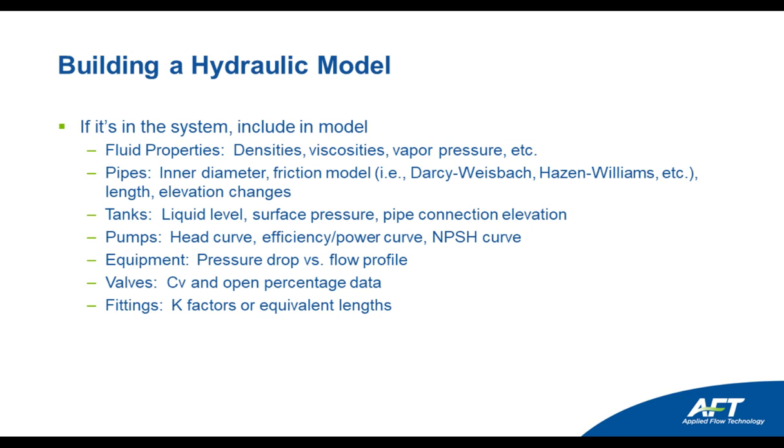Now, let's say that you have included all of this information in your hydraulic model, and the flow model results are still not completely matching your measured data. Well, that could be indicative of a few different things. Maybe something might not be modeled right, or maybe there's missing data. Maybe from a drawing, you're capturing a certain diameter of piping in a particular header somewhere, and at some point, maybe they changed the piping out in the plant and didn't update the drawings.